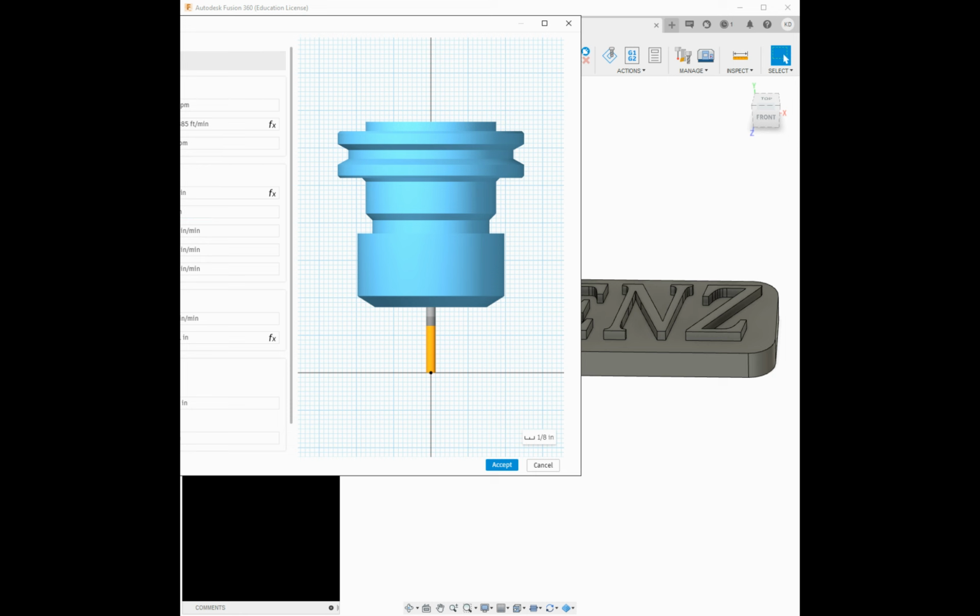And for plunging, which is essentially drilling, there's a feed per revolution that you can do too. And usually this is a shade less than our horizontal feed rate. So for a basic setup, this is going to work just fine, and I'm good with this.